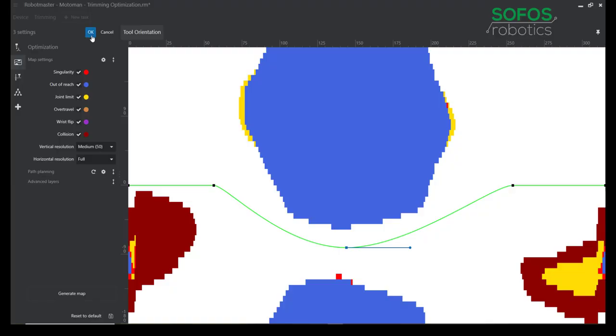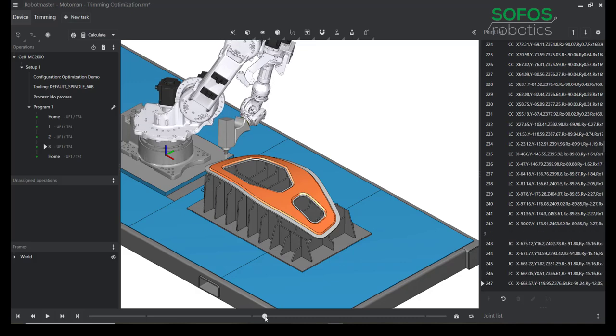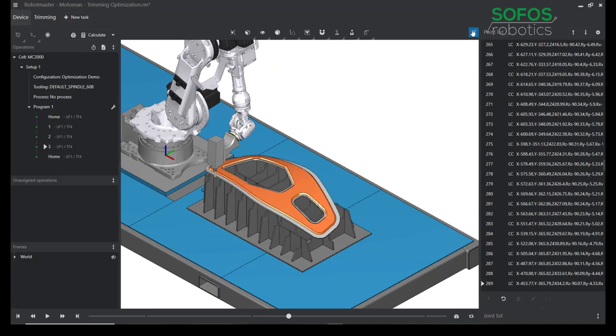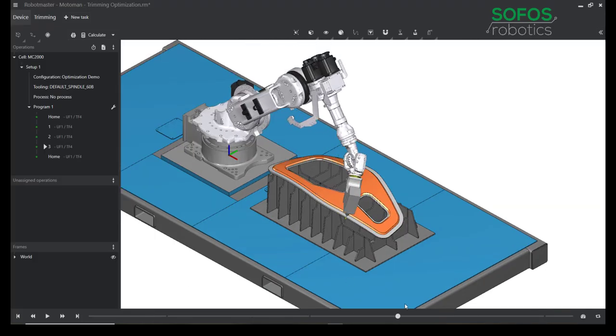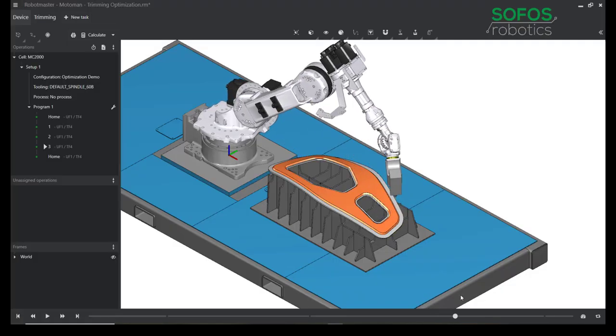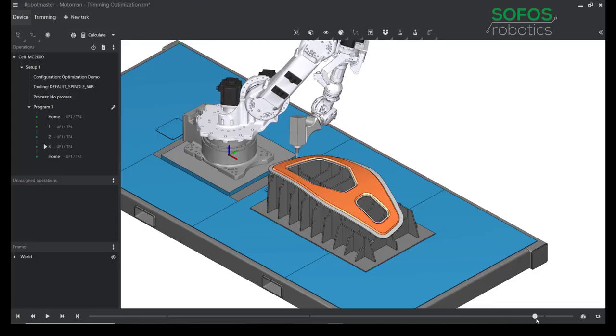And so if I go ahead and click OK, you can see here we've gone from having a red dot to a green dot, indicating that all of our kinematic issues are solved. And if I simulate through, you can see we're starting at that -90. And as we continue down that path, we'll see that wrist open up. And as we get close to the robot to avoid collisions, you'll see it'll curl back in on itself.